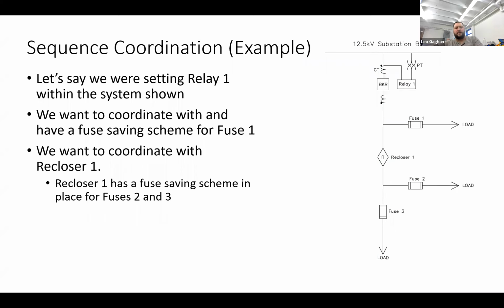So sequence coordination. Let's say we were setting relay 1 on the right. We would want to coordinate with and have a fuse saving scheme with fuse 1 that's feeding its own load. And we would want to coordinate with recloser 1. Now, recloser 1, let's say it's existing and it's already got a fuse saving scheme in place for fuses 2 and 3.